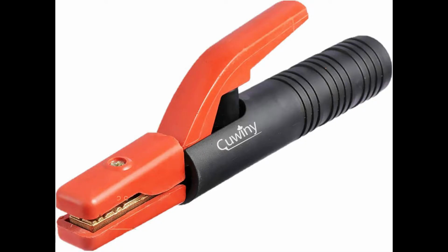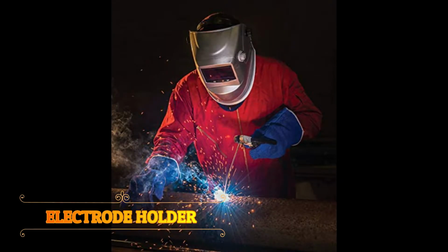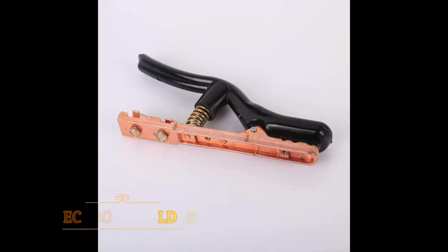The next one is electrode holder. Electrode holder is used for holding the electrode manually and conducting current to it. These are usually matched to the size of the lead, which in turn is matched to the ampere output of the arc welder. Electrode holders are available in sizes that range from 150 to 500 amps.